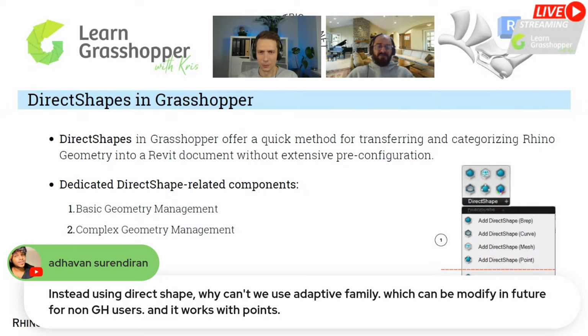But when it comes to unconventional objects or those which are hard to model in Revit, it's better to do that in Grasshopper. Grasshopper and Rhino have robust capability with geometries and curves. You can easily manipulate and create very complex geometries in Grasshopper, and unfortunately you don't get this kind of freedom or robustness using Dynamo or the native Revit families.